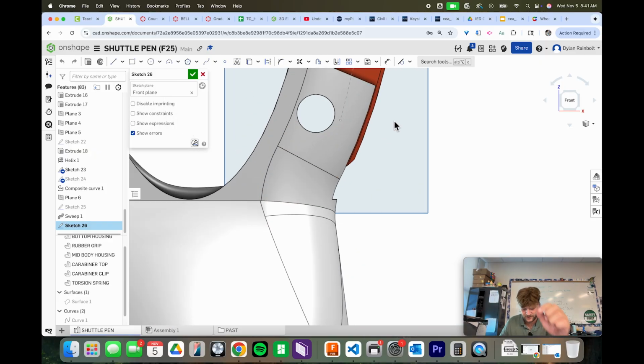Then what we're going to do is use the values that we got for our dowel pin. The dowel pin, in terms of the length, as I'm measuring that out here, I've got 0.257 inches. Perfect. And now we can also get the actual diameter for this. If we look at the diameter of our dowel pin, the diameter is 0.057 inches.